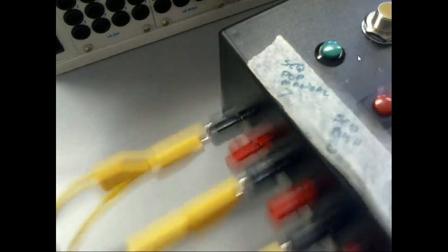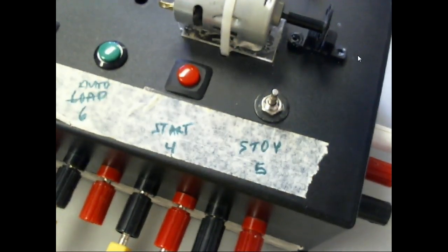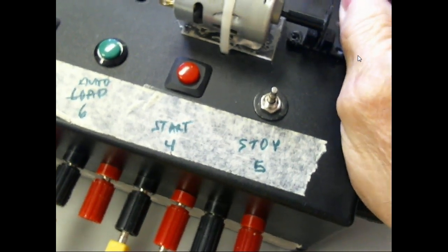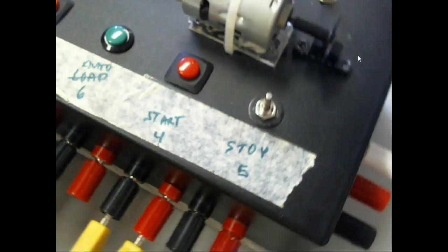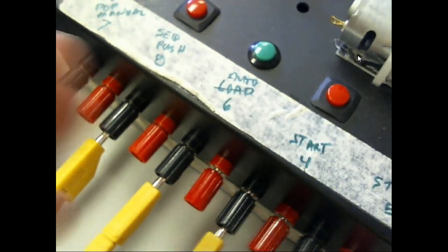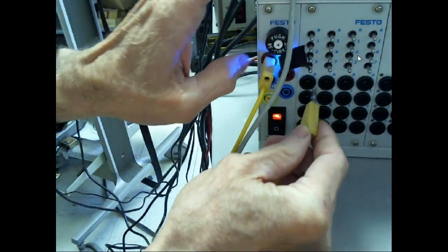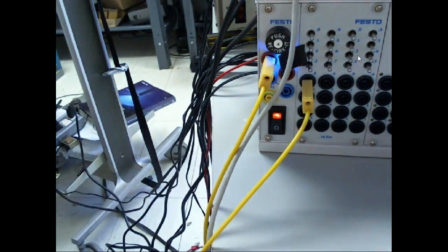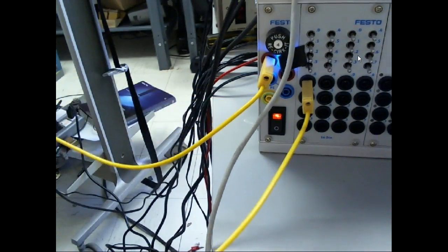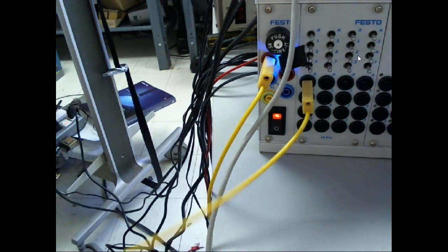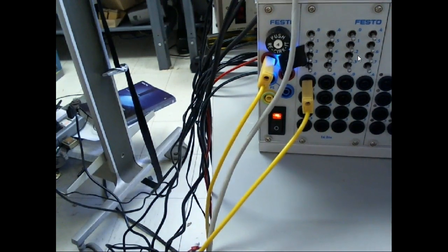Now we're using 2 push buttons. Right now we're using the normally closed push button. So what would I do now? I would take this wire right here and hook it up to input 0 on my PLC. This is why we do this, because it brings the inputs of the PLC down to these guys, and then I can control the switches. So that's my normally... where did it go? Oh, I missed my column.